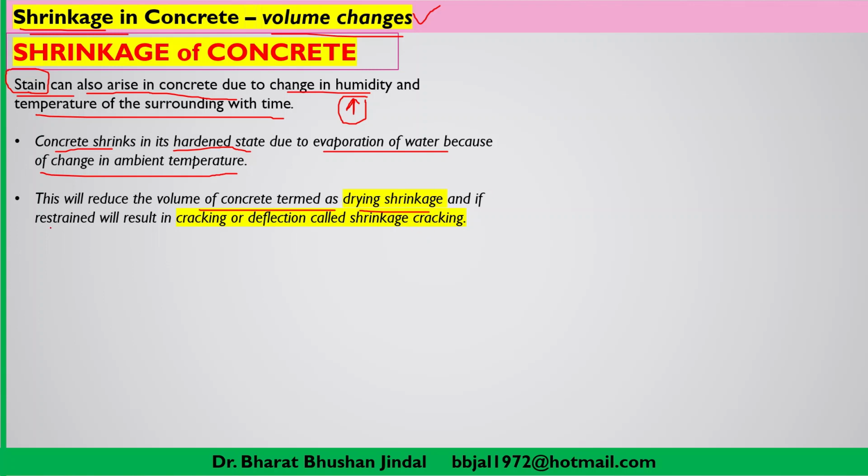And if that particular structural element is restrained to shrink, then what will happen? There will be cracks or deflection, and that type of cracks are known as shrinkage cracks. Earlier we have gone through creep, now it is shrinkage. So cracking due to shrinkage of concrete is known as shrinkage cracking.